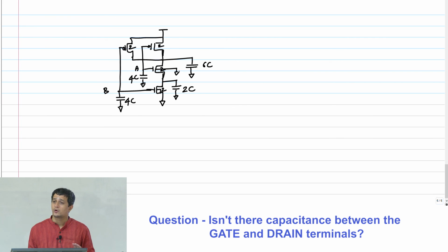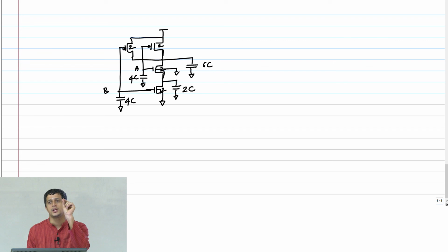There is a capacitance, so that's what I told you. That becomes like a capacitance between the input and output. Now that you do Miller capacitance and split it. So I'm saying you lump all of them. Effectively, it's like 1C here, and the drain also has the same C. Correct. Any other questions? You can bring it as close as you can. Effectively, it will be like one diffusion. That's all. You try it in the layout and see, you'll know.